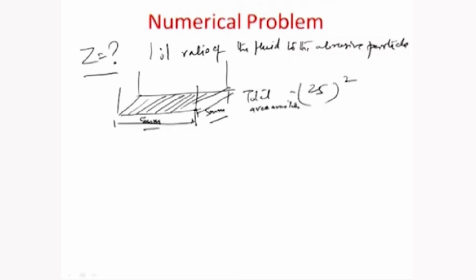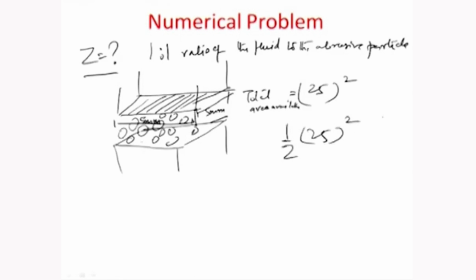available, and this area has to be flooded by a slurry between this and the workpiece surface which is situated down here. So this whole volume has to be filled by a slurry which essentially contains these particles in the ratio of 1:1, meaning thereby that 50% of this area, half of this area, needs to be inundated with particles, and the particles, as you know already, have an average grain diameter d with an area of pi by 4 d square, or pi (d by 2) square, pi r square.